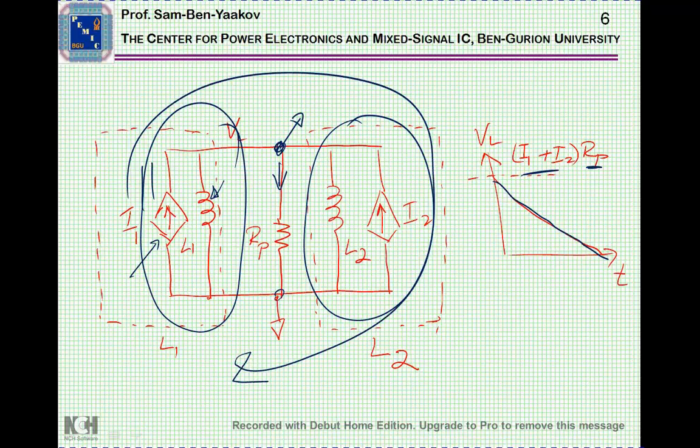So what we will see is that one inductor will have, say, current in this direction, and the other one will have current in this direction. So there'll be a loop of the current, no current in this branch, and this is sort of a short on the inductor, which ideally, if there's no resistance, the current, of course, will persist.